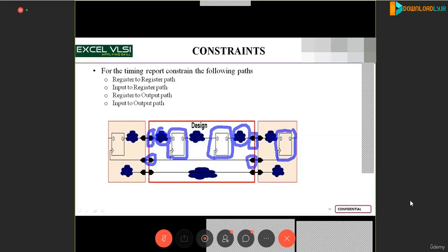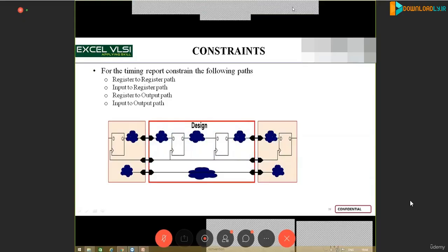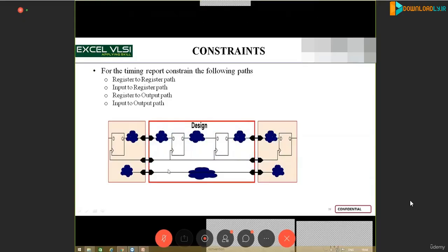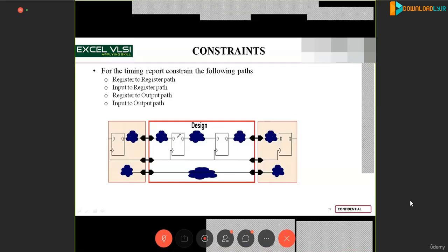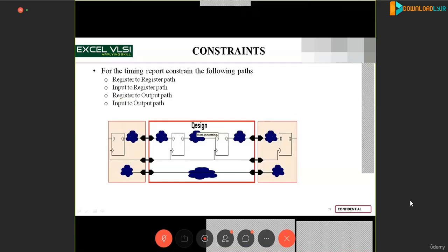So how we are defining the timing value, how we are relating the timing parameter for those particular ports, is we are segregating the complete circuit into 4 different parts. While doing this timing calculation, we basically report this gate level netlist in these 4 parts.